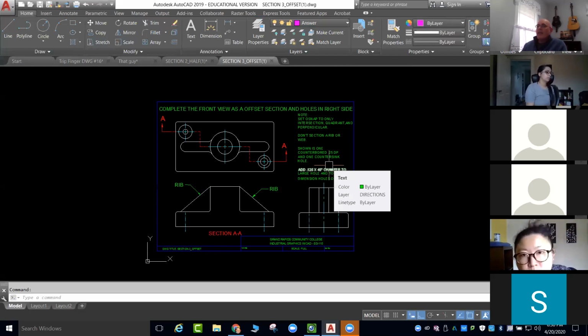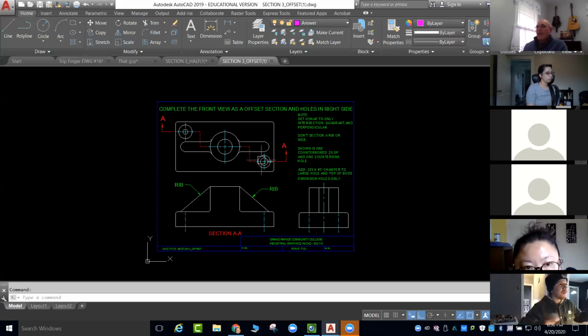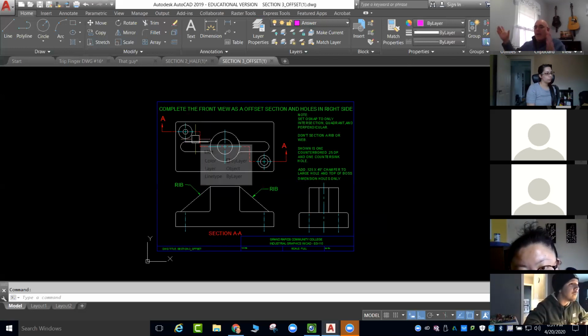But as you're looking at this, which one looks more like a countersunk from the top? Is it the upper left-hand corner or the lower right that looks more like a countersunk hole? Lower right. You think the lower right looks more like a countersunk or a counterbore? Counterbore. The one up top looks more like a countersink because it's got a bigger head with a smaller shaft, where the counterbore looks like it has a bigger shaft with a recess in it.